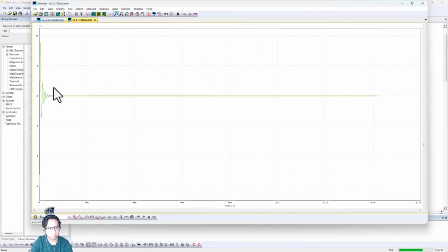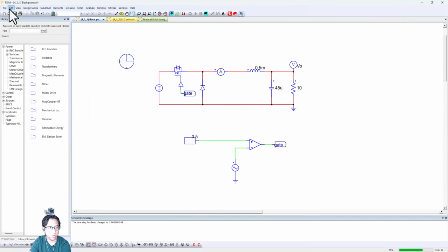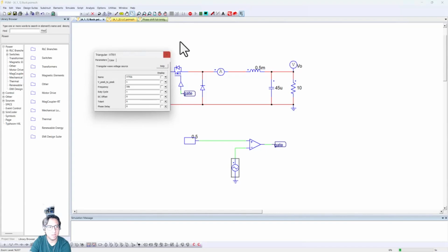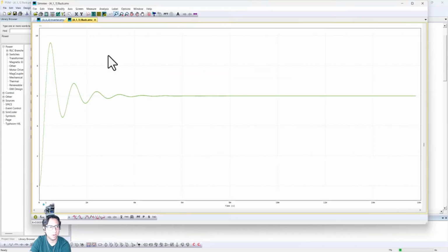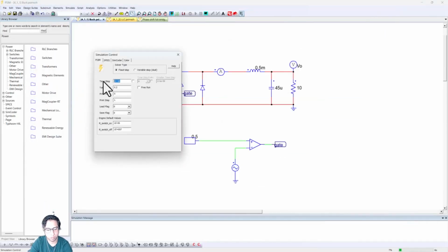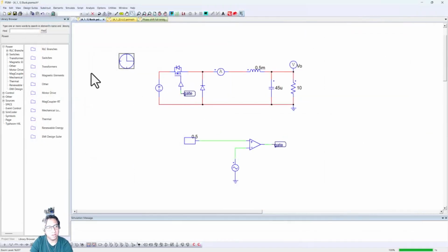We see that the waveform is correct, and if we look at the gating waveforms, they are going to be correct. But to fix this and to make this quicker, we just need to place this onto 1, and then change the time step to the original one. That's right, which I didn't do. Now it's fast, almost instantaneous, right?